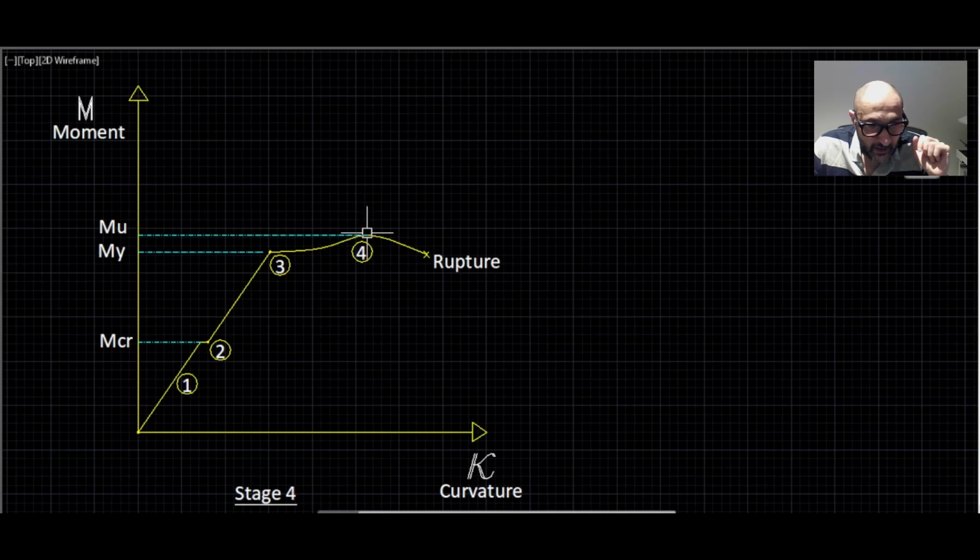The point that we are interested in when designing beams is this moment corresponding to this peak level here, this little curve here. This is called the ultimate moment capacity, or the nominal moment, and it is written generally as M sub u. At the ultimate moment, it generally means that concrete crushes at the top in compression. The maximum concrete strength, f'c, would have reached that capacity. At the yielding capacity, we must make sure that the compression has not reached it, but at ultimate moment, we expect that f'c would have been reached.